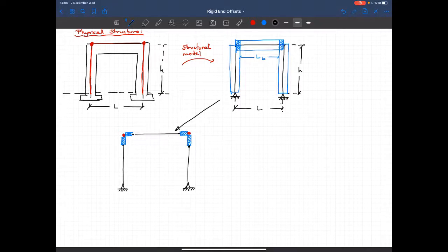Okay, now if you say that that's the depth of the beam, so if I just want to mimic this modeling, this distance would be equal to d over 2. So a portion of that column is rigid, and the part below can bend more flexibly than this part, so I just represent its behavior by a rigid member.